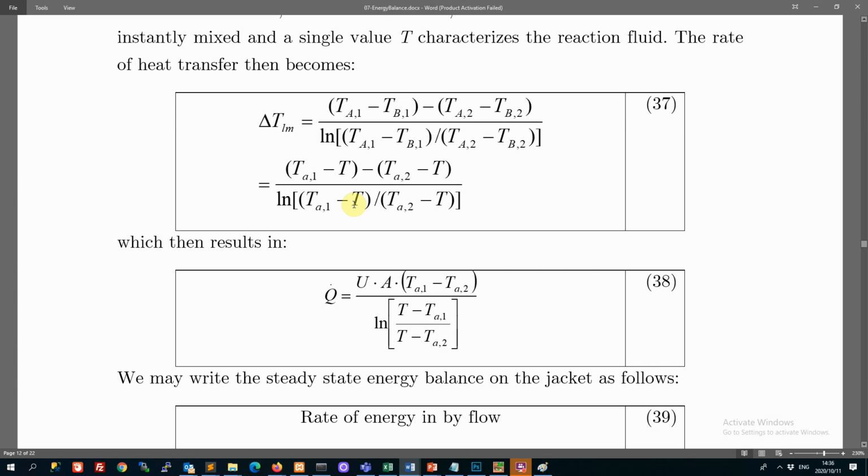Okay, so that's how log mean temperature difference looks here. Another thing to note is we know this expression is precise in the case of a double pipe. So when you first derived this expression, it was for either counter or co-current flow in a double pipe, and this was exact. You derived this and you proved this was true.